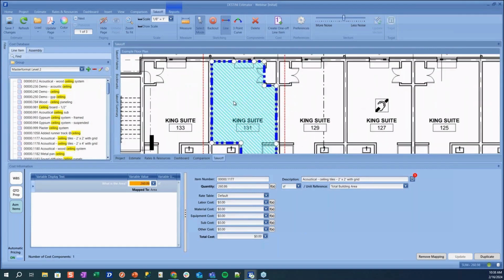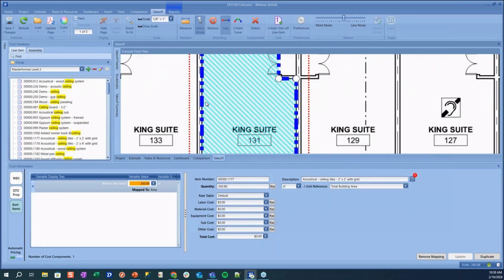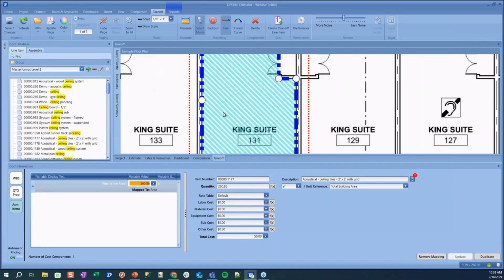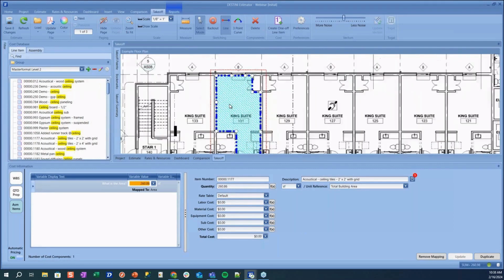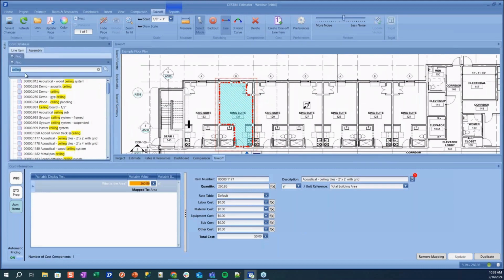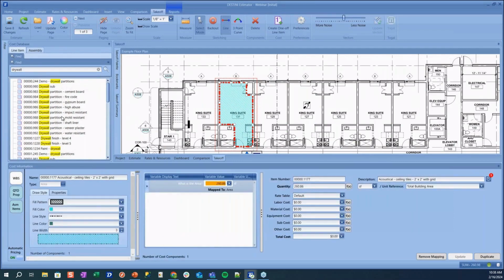takeoff. So again, if we want to add points to a takeoff, we just left click on the takeoff that we want to add a point to, and then right click where we would like to add our point. So what we'll go over next is how we can do takeoff and then have the ability to split that takeoff after we have completed it.